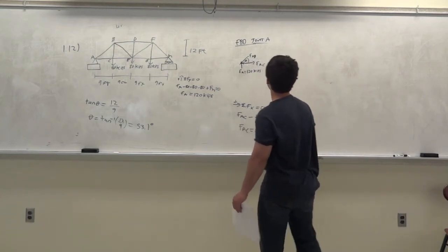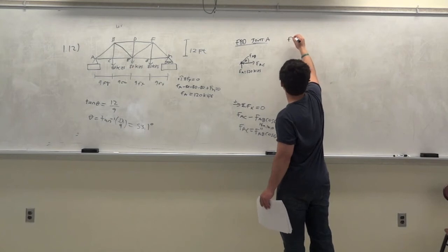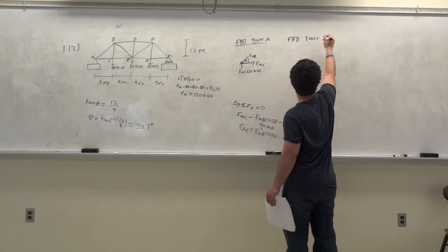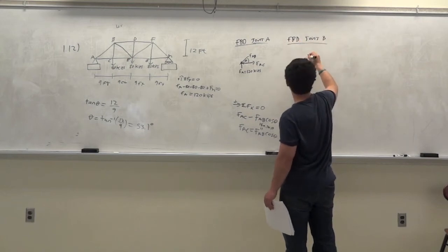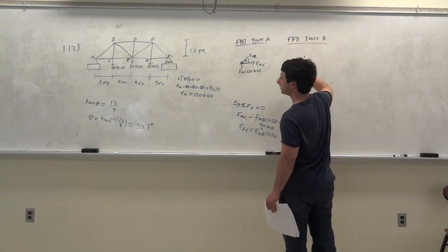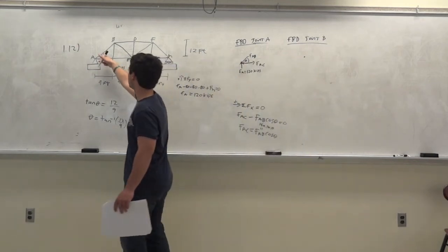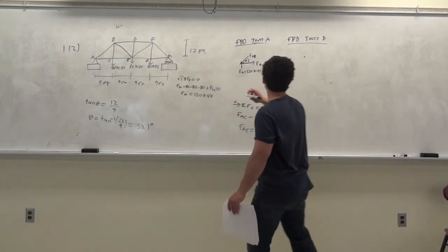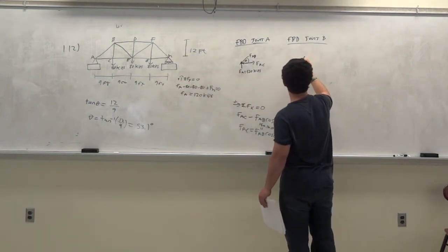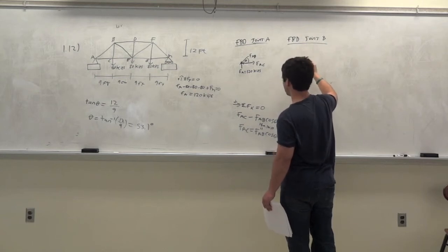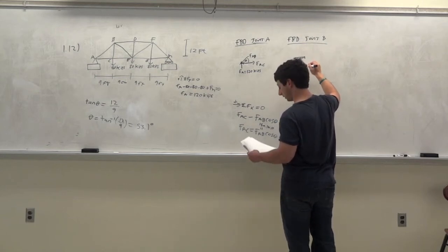I should keep this free body diagram. So, okay, free body diagram of joint B. Let's draw joint B. Joint B is here. Okay, so we drew this one in compression. This member AB is in compression, so this has to be equal and opposite. So this is FAB. This angle over here is theta. It's the same angle, and FAB we just found to be 150.1 kips.